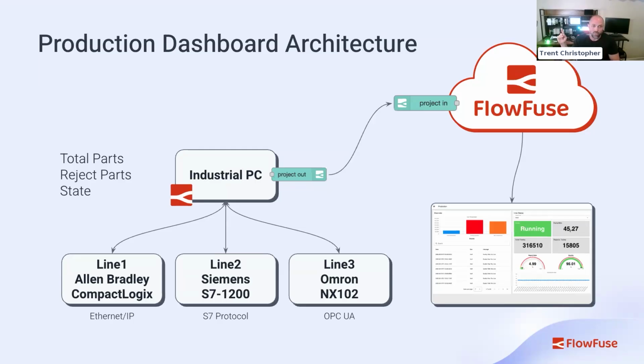So my suggestion is to go with something that's industrialized. You can look at OnLogic. There are plenty of other ones out there too, Advantech, Phoenix Contact. Just look for Intel-based platforms that have a decent amount of RAM, minimum 2 gigs, but pushing 4 to 8 if you're doing a lot of devices. If you want to do more storage, just grow the resources. You can also run multiple instances on these devices if you need to distribute some of the workload between multiple Node-RED instances.